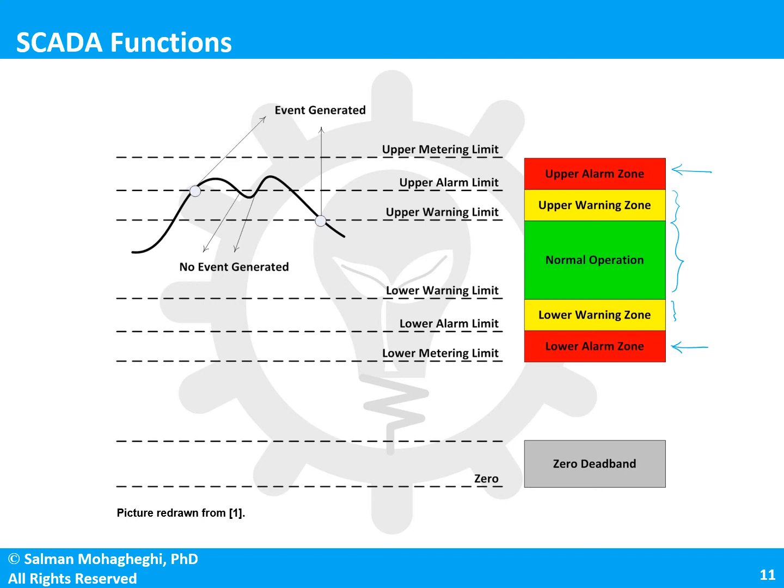If your measurement value, which in this case is this line, crosses one of the thresholds, an event is going to be generated. No new event will be generated until another threshold is crossed. Notice here that you go up and down, slightly above this threshold and slightly below this threshold, but because you're not crossing other thresholds, no event is generated here or here. However, when you cross another threshold, which is this new one, a new event will be generated.